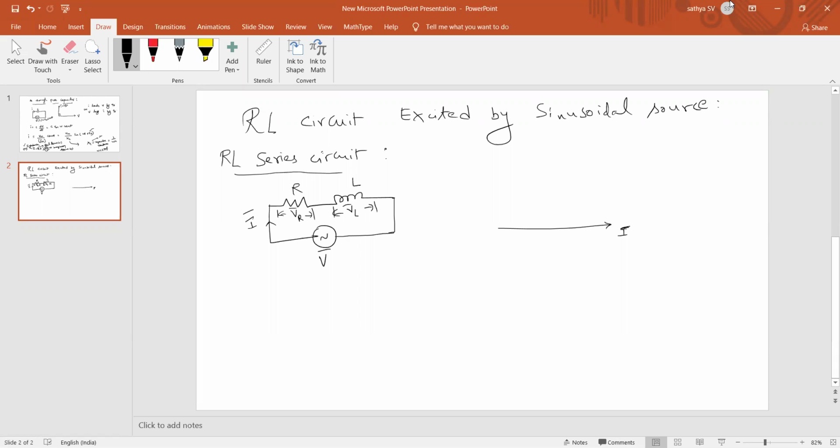In those individual parameters, if you consider the resistor, which is excited by some voltage source and the current passing through as capital I, are V and I in phase or any relation, lagging or leading? In phase. Very good. Which are in phase quantities for resistor. So that means, shall I mention VR here? The voltage present across the resistor. Now the resistance part is finished.